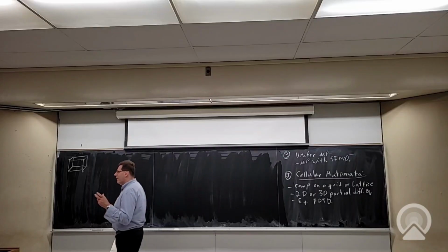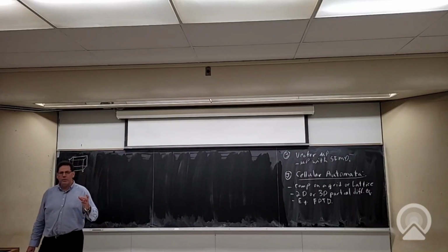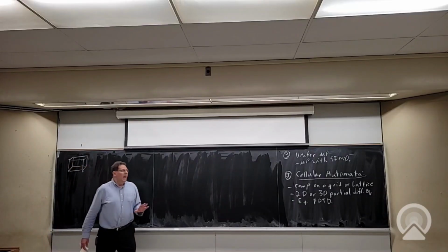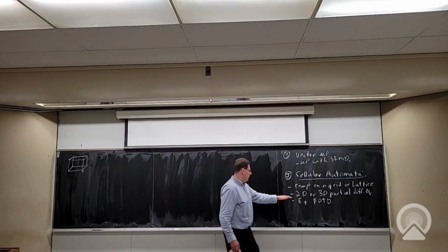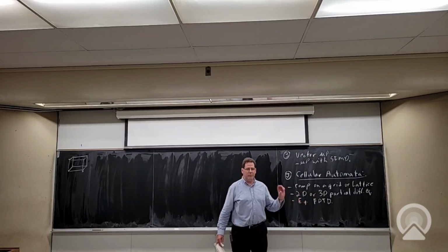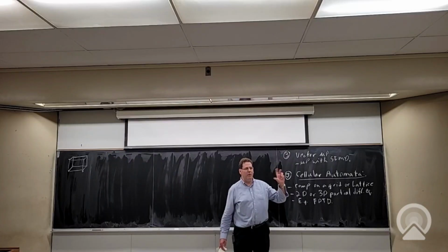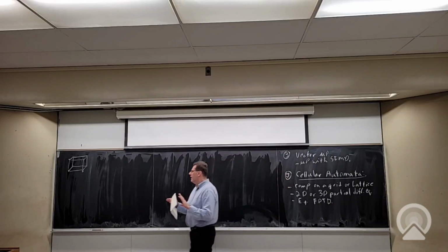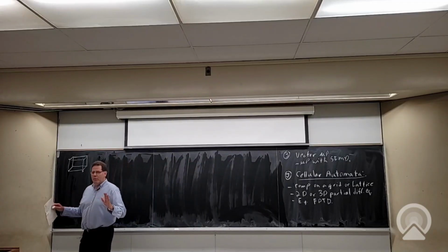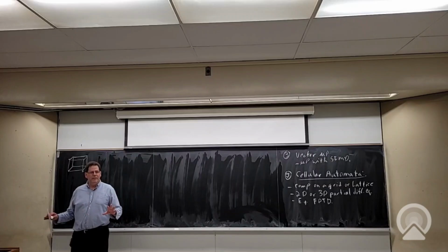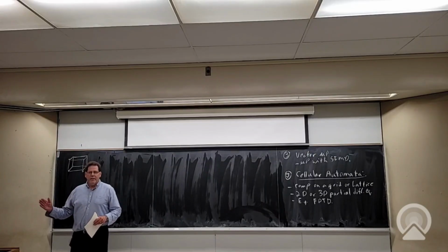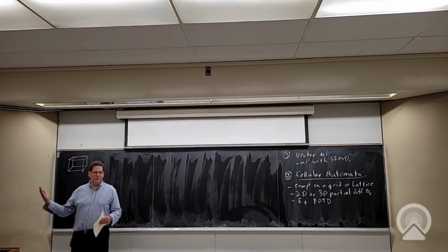This is a method that you can actually use to solve complicated partial differential equations that you can't analytically solve, which is most of them. You basically make a grid of points and you turn the partial differential equation into difference equations. So it's no longer infinitesimal differences, it's now small differences. If you make a big lattice, a whole bunch of points, you can model a pretty complicated geometry. And you can basically just walk through the geometry applying your difference equations in space and in time, and you can see how the physics of your problem evolves.